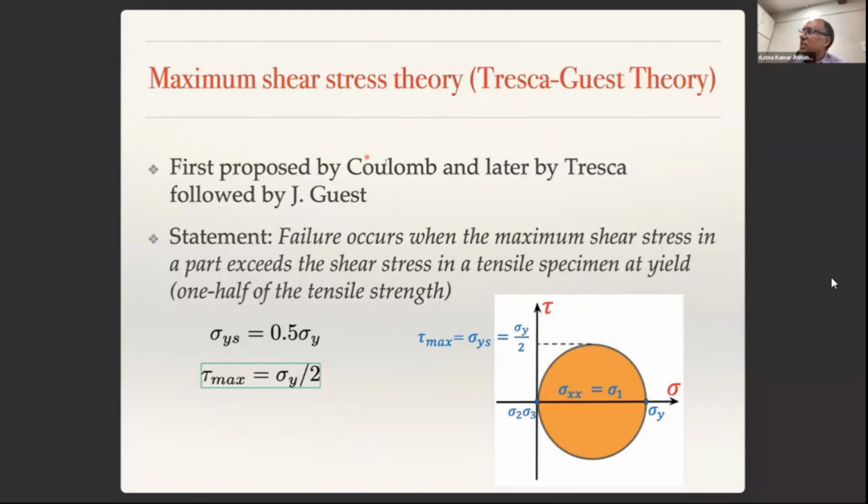They used the shear stress theory, but for metals, ductile materials, the description was mostly formulated by Tresca and Guest, and hence it is called Tresca-Guest theory. And that is the version that we are using now. So what does this theory say? It says the following: failure, in this case, is the onset of plastic deformation, right? So this happens when you're applying a three-dimensional state of loading in a component.